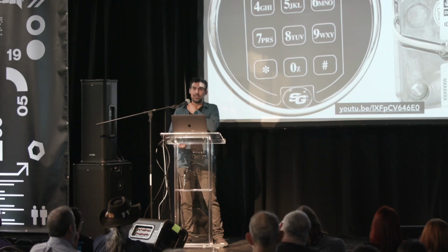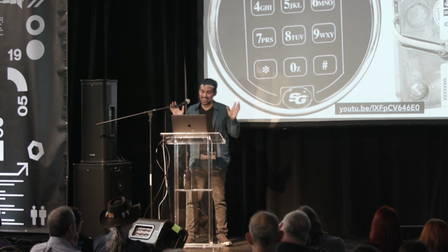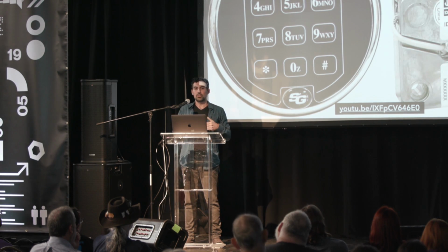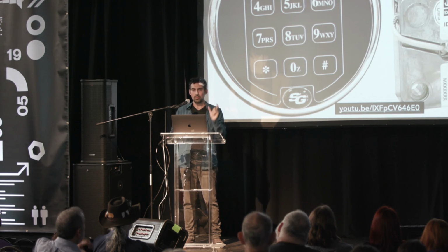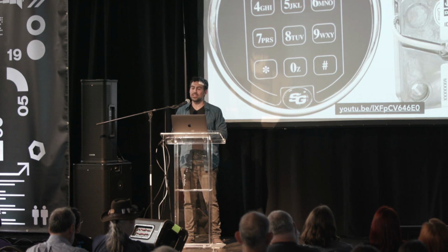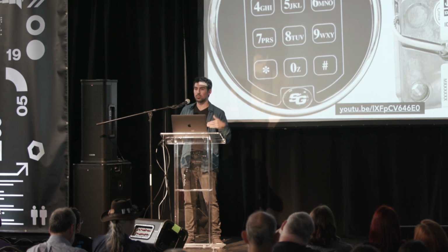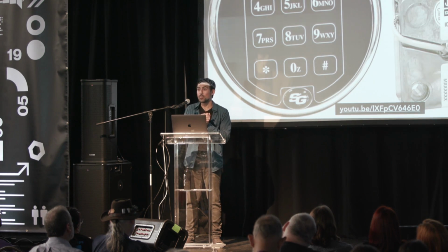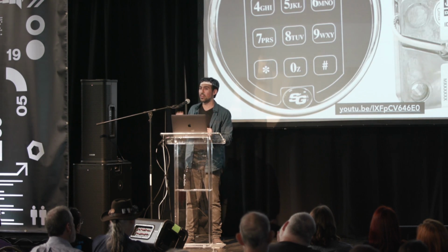But the interesting thing about EEPROM, it's electrically erasable programmable read-only memory, which makes no sense because how is that read-only? We should just call it something else. But the way EEPROM works is that in order to write to it, you must first erase it. So let's say you enter an incorrect code, and that EEPROM turns to 1, then another, and it turns to 2, and you're about to enter another code that's about to lock you out for 5 minutes.